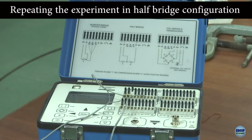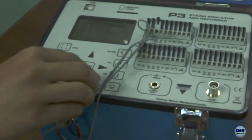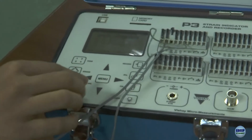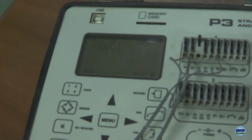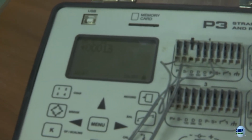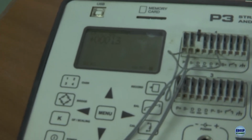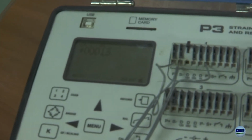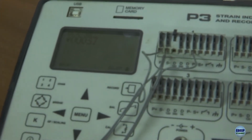Now, I have connected the tension and compression side strain gauges in the half bridge configuration. In the bridge configuration, I am changing it to half bridge and balance the circuit initially. For a 50 gram load, the strain in the aluminum in the half bridge configuration is shown on the indicator. For 150 grams, the strain corresponding to it is shown.